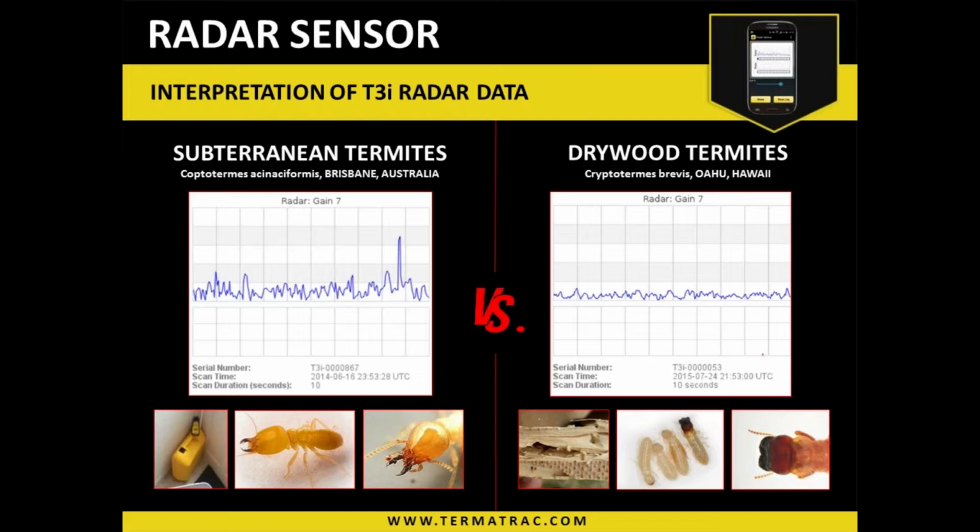The tapping technique to see for changes in the patterns also helps us to alleviate any mechanical vibration which we may be experiencing on our patterns. If it is mechanical vibration, for example an air conditioner attached to a wall that we're testing, when we tap on the wall, that pattern won't change because it's a mechanical object.